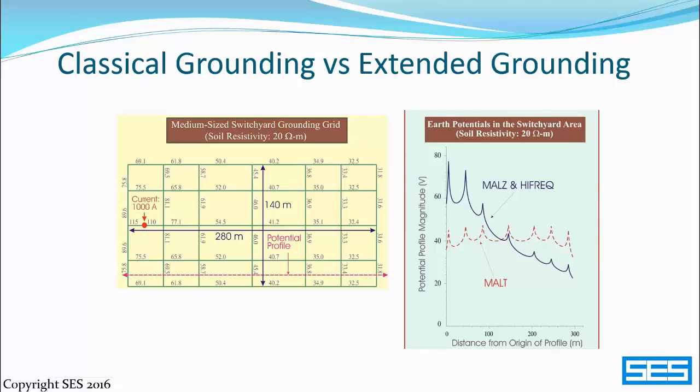In practice, it can be quite hard to predict in advance whether or not the grid will be reasonably equipotential. The prediction is made particularly hard in multilayer soil with high resistivity contrasts between layers. On top of that, it's hard to be reasonably conservative. In the case I'm showing here, the soil potential is overestimated on one side and underestimated on the other. Even without changing the soil resistivity, we can see differences between the results reported by the various modules in the case of a large grid.